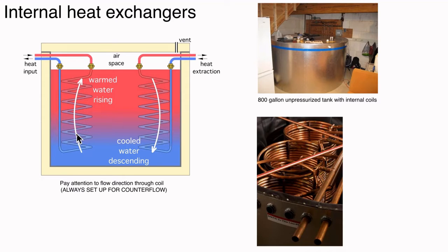Now, what are the practical concerns here? Well, the heat transfer from the surface of the coil to the water in the tank is by what we call natural convection. Natural convection is relatively weak compared to what is called forced convection. I've got more slides that we're going to get into a little deeper, but because we're relying on natural convection, we have to have a lot of surface area to get the heat transfer rate that we're looking for.